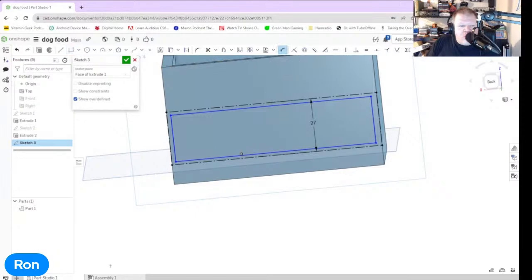So we know that we don't want to make the full cut into the plastic. I've got plans for that, trust me. So I'm going to hit on the side here, and I'm going to hit the construction line. If you notice, we can use the construction line with it to make our box. So instead of that, it's going to be 5 millimeters away from it. I'm going to click on this one, and I'm going to click on the construction line, pull it across, make that 5 millimeters also. So we're not cutting into that plastic. We're going to do something different. I'm going to show you guys in a second what I plan on doing. And we know that we want this and this to be 27.